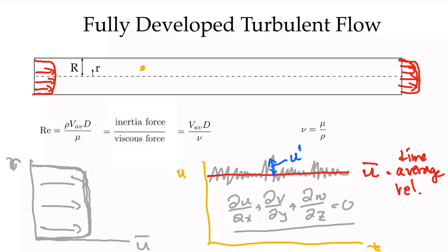And that tells us a couple of truths about turbulent flow. One, it cannot be steady. There is a time dependence, which we can average away and look at the time average. But there is an unsteady component to it, and it is three-dimensional. You cannot have a velocity fluctuation in just one component. It will be in the 3 dimensions. The time average velocity can be one-dimensional, but the actual velocity signal will be a 3-dimensional velocity signal. So we know that actual turbulent flow is 3-dimensional. It's changing with time. And when we take the time average, we see that there are higher shear stresses, and so we expect higher pressure drops in turbulent flow.